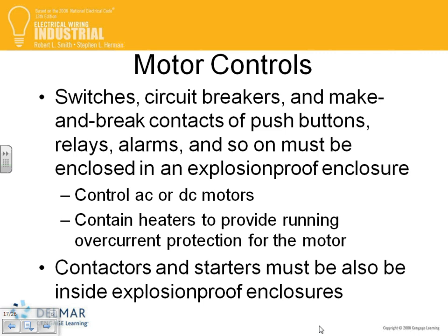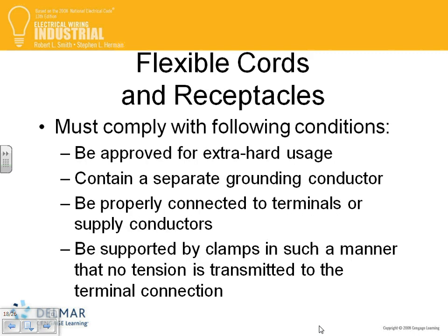It must also be explosion-proof. The enclosure has to be explosion-proof. The devices are the same devices, guys, but they put them in an enclosure so that even if there's an explosion, it will be contained inside the enclosure. And by the time the hot air seeps outside that enclosure, the temperature will be low enough that it will not ignite the surroundings.